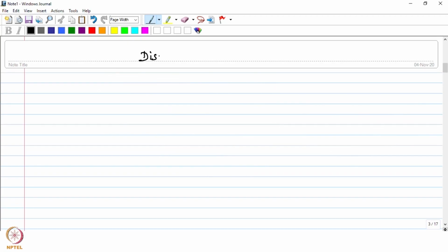The next important aspect, as I said before, is the distribution of particles. The reinforcement particles should be distributed uniformly, and it should be ensured that there is no agglomeration or clustering of particles. Okay. So whether the particles will be homogeneously distributed or will be agglomerated, that would depend on the solidification behavior of the composite material when you actually cool down the entire system after adding the particles into the molten metal. Okay. So let us talk about that as to what happens during that process of solidification when you have these particles suspended in the liquid metal.